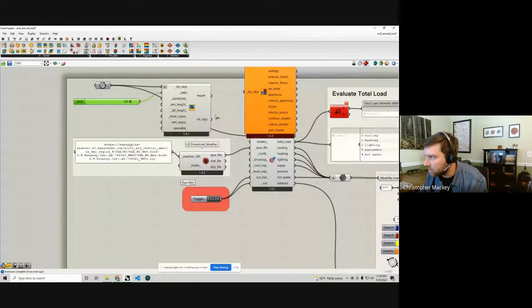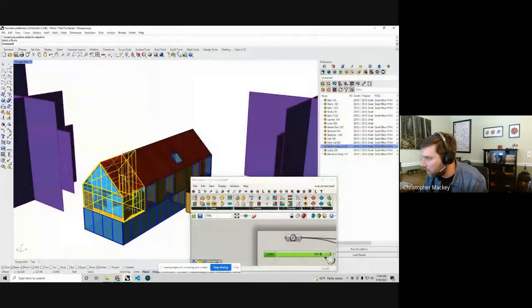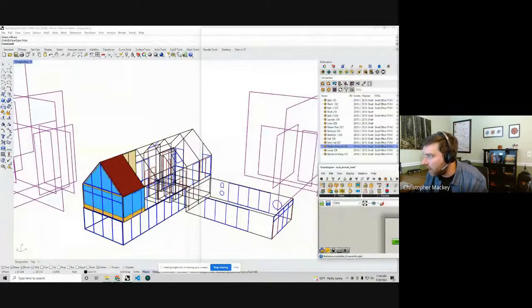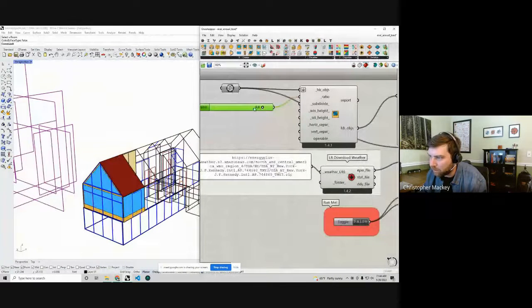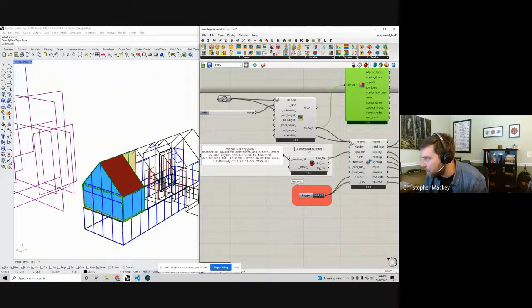and that's actually going to result in, why don't I even preview this here. Let me turn the Pollination Rhino preview off. Right, you can see I can just as easily use all those nice parametric features. I can dynamically adjust the glazing ratio of this room very nicely. Let's say maybe I'll put it at 90%, really highly glazed, and I can connect up this edited room to that same annual loads component.